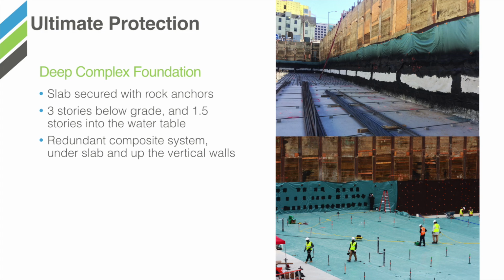The detailing needs to be perfect. Around each one of these penetrations, if the detailing is not done perfectly, leaks will be visible inside the basement. For this typical application, or in an ultimate protection environment, a 16 mil thermoplastic base sheet, 100 mil application of polymer modified asphalt, and a bentonite protection course provide an ultimate level of protection.